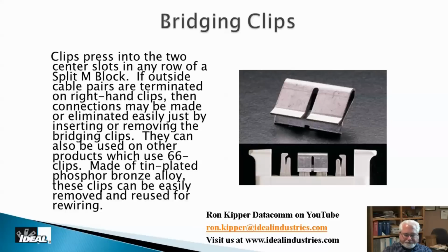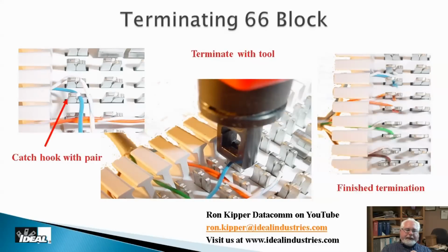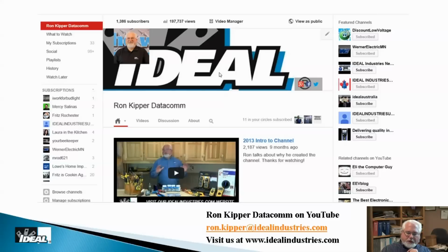So typically we bring cable from one side of the block, catch these little hooks on these little connections inside that 66 block. A punch down tool, with the 66 bit in, will drive that wire down into that IDC connection and make that connection for us. And in this case, usually trims off the conductors for us as well. But as I said, there's lots of ways of wiring 66 blocks. So you might look into that if maybe you're doing a strip mall or something like that. I don't know. All right.